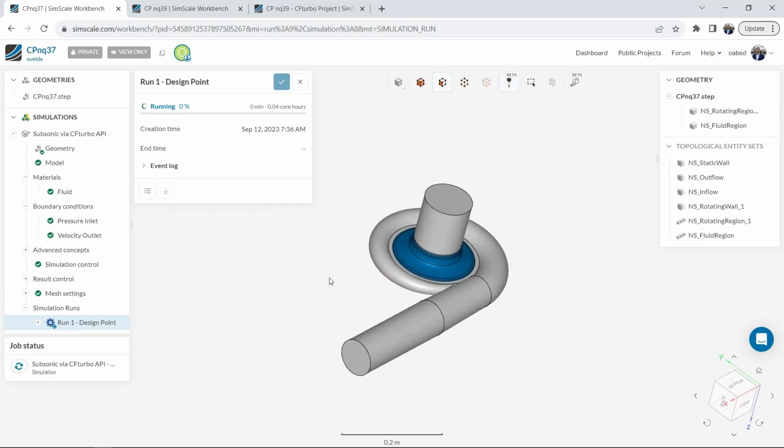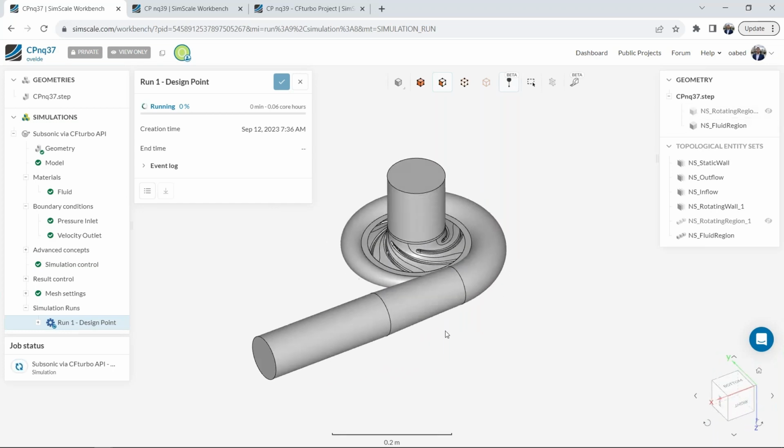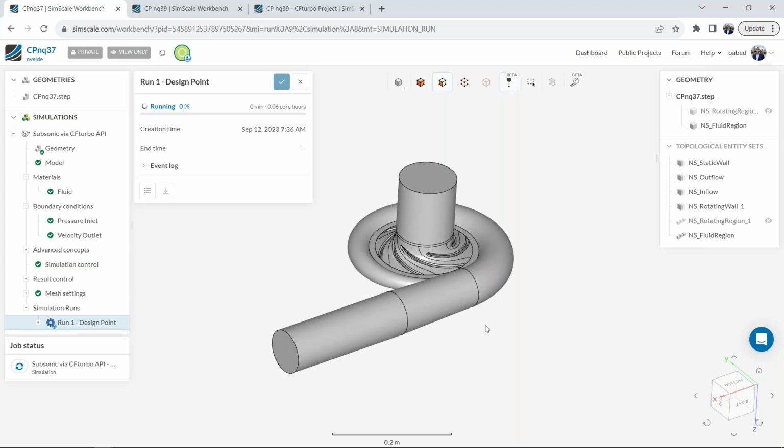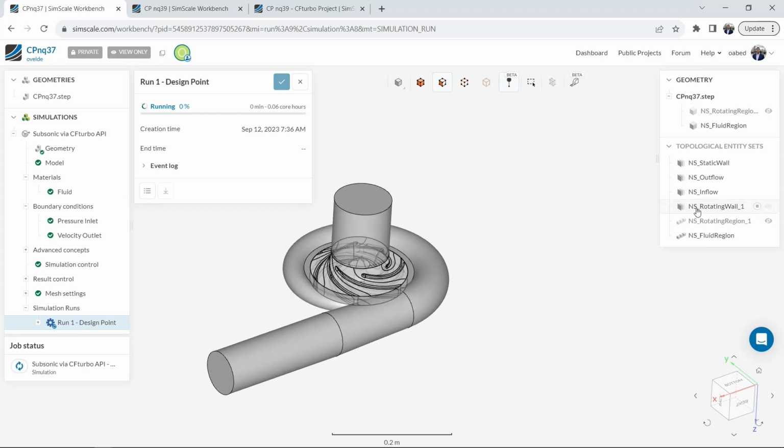what we have done. So we can see here, this is the original flow domain, the virtual flow domain that Oliver had imported into SimScale. Of course, all the naming conventions, like the inflow face, the outflow face, all the static stationary walls, as well as all the rotating walls of the impeller rotor, have been mapped appropriately so that it's very easy for you to modify your setup beyond what's automated for you, to progress on further iterations, or if you want to set up your simulation in a slightly different manner.